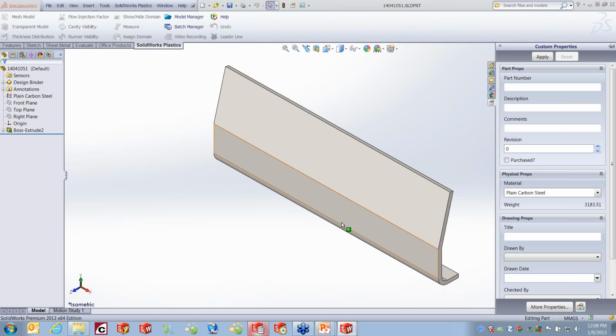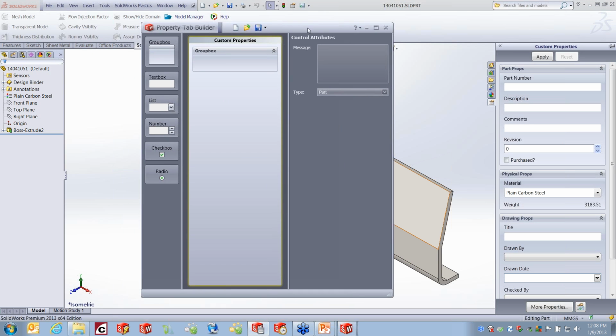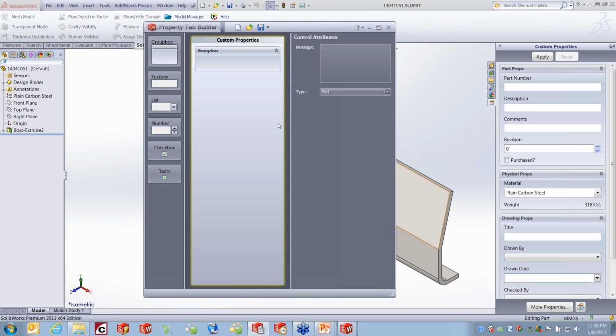In your SolidWorks Start menu, you're going to find a tool under SolidWorks Tools called the Property Tab Builder. Now that's what allows you to build this interface that you're seeing. The one that I'm showing you is straight out of the box from SolidWorks. So just to give you an idea how this works, we're really not talking about this tool and functionality more than how do we enter data. But first of all, you have to specify, is this for parts, assemblies, drawings, or specifically to welded structures inside of SolidWorks. And you group items together within the system.